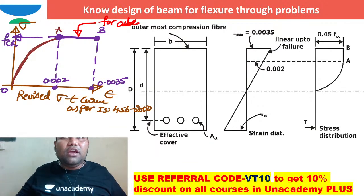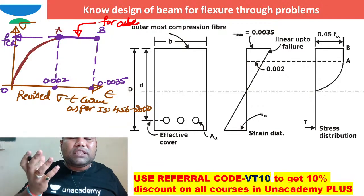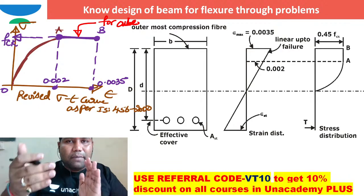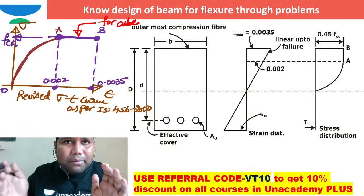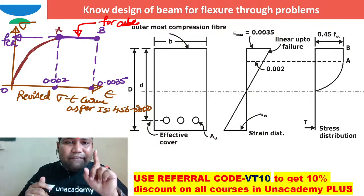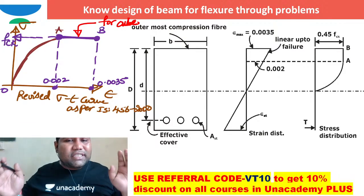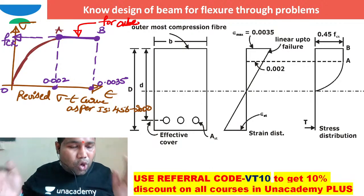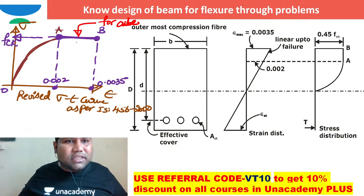I hope you can see the difference when you take a cube and a real structural member. The size of the cube is 150 millimeter by 150 millimeter by 150 millimeter. In real structures, are all the structure sizes 150 by 150 by 150 millimeter? Is the shape of the structure also just like the cube? No. This is the stress strain curve for cube. I want to draw the stress strain curve for concrete in structural members. So how can I take this? FCK is the failure strength for concrete for cube.